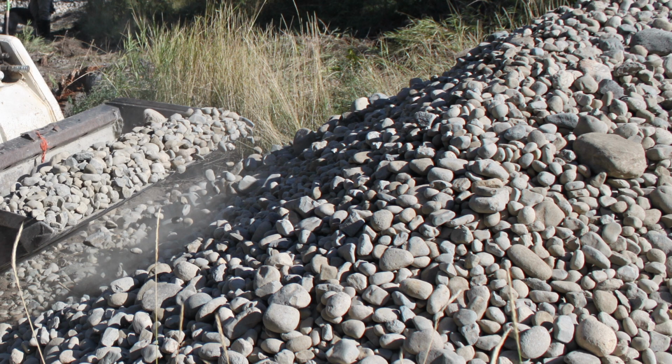See how this rock is rounded? This is called river rock. It's best to use angular or fractured rock to armor a spillway. This is because they fit tightly together when pushed into the ground. Unfortunately, the quarry did not have angular rock, so I was happy to get the rounded rock.